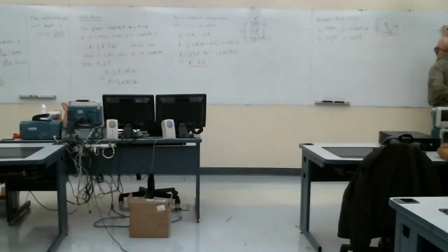It would be R inner to the load, and then R outer. So the resistance of our coax per unit length is actually the sum of those two resistances. They may look like they're in parallel, but they're actually not.